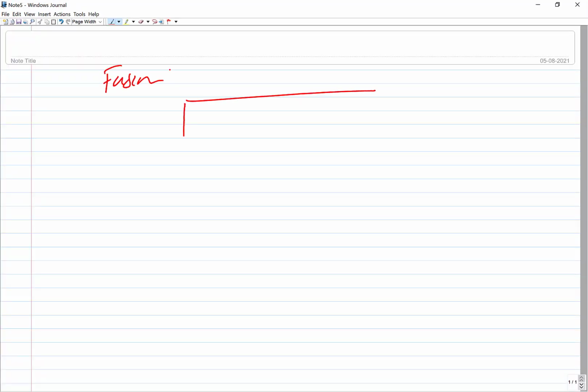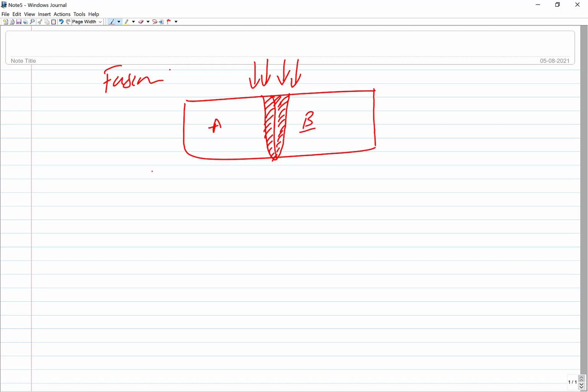Lastly, here it is about the fusion. The fusion is a very simple one. Here, for the two components to be joined, you apply the heat in a very controlled way. The idea behind this approach is to have controlled melting of the edges of the plates, the edges of the members of the components to be joined, and subsequently, whether they are of the same metal or different metals, they will mix with each other, and after solidification they will produce the weld joint.